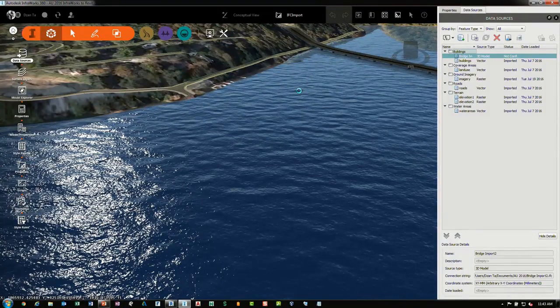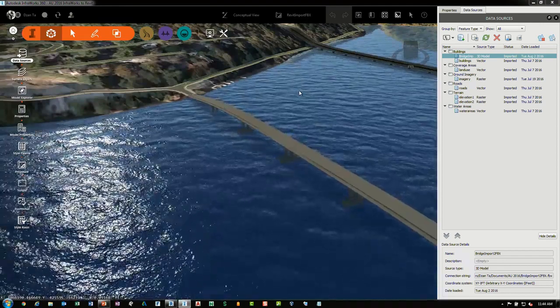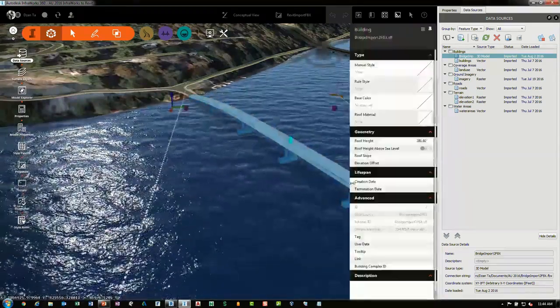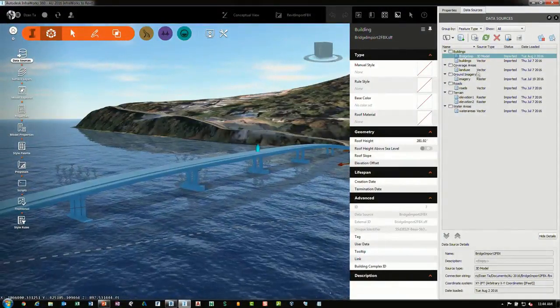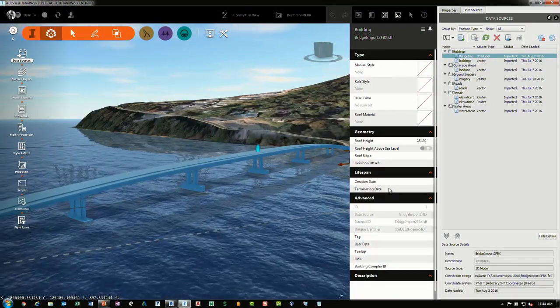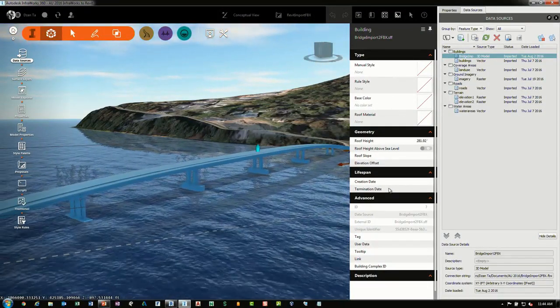The FBX file format is something that most people typically default to because it actually retains material, content, and a lot more intelligent information. So taking a Revit file and exporting it as FBX is very easy. And taking the FBX file and bringing it into InfraWorks is easy. And it actually accepts it fairly well. Let's give my machine a second to process. And so you'll see the file is also brought in, and it also has basic capabilities such as grip manipulation, placement, property information as well. And so it works. The FBX file format works fairly well. Okay.